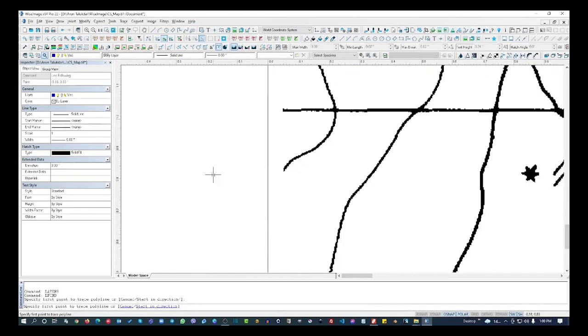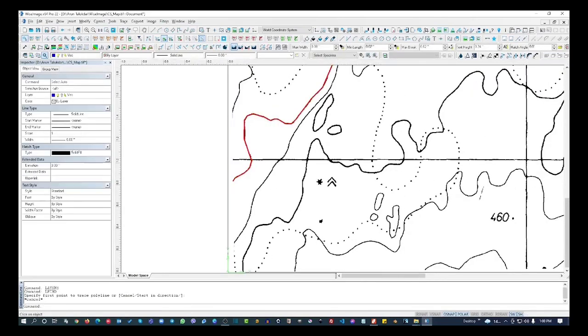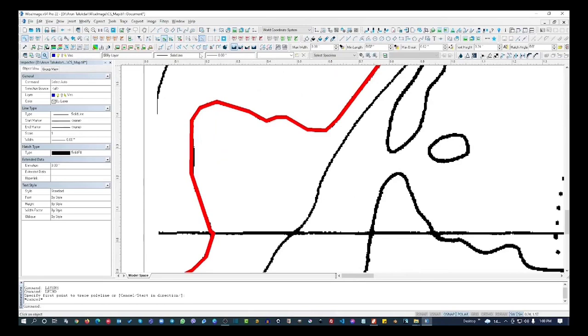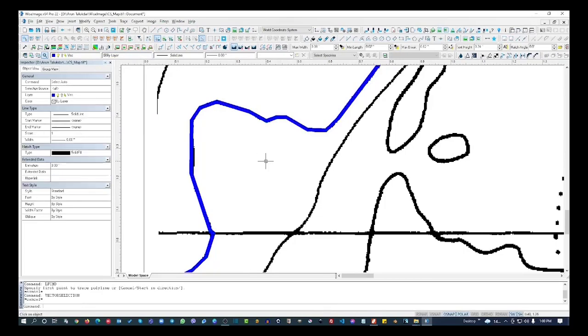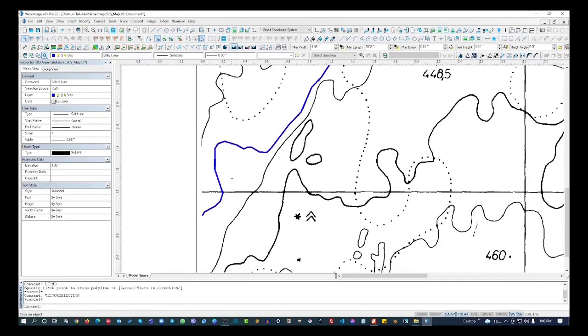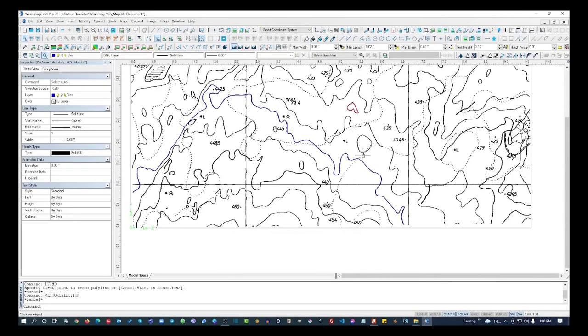So this is one more, right? This is my contour now. I can select the contour like this, and this is the forced color. I should use the by-layer color. So now I have the entire contour ready for me. Like this, we have different tracing tools that can be used, and you can change the way you actually draft things in a CAD system.